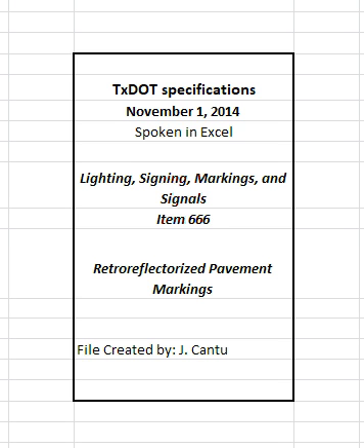4.3.3 Bead coverage. Provide a uniform distribution of beads across the surface of the stripe for Type 1 and Type II markings, with 40% to 60% bead embedment.